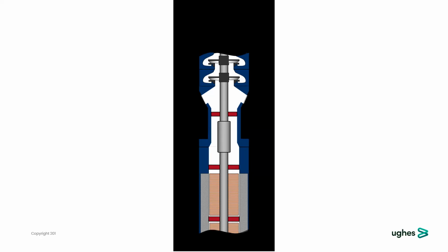So the well fluid will go to the pump while it's already connected to the motor. Well fluid will go on top of the motor and lead to a burned motor immediately. So you have to think about why it's bad and why we cannot connect the pump and the motor together directly, because the well fluid would enter the top of the motor and burn the motor immediately.